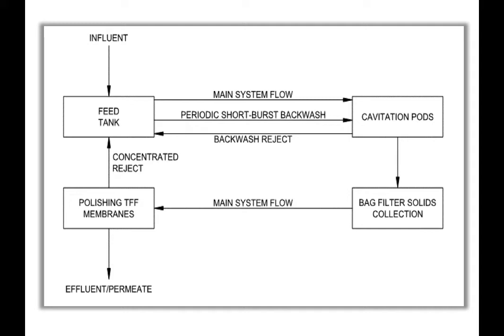And what happens is all the dissolved ions that are in the water start to plug those pore spaces. So every 5-10 minutes, whatever it is, you've got to run the whole system backwards. And that takes time, it takes power as well. And then you end up with this reject brine that all RO plants struggle to figure out how to deal with, that particular waste.